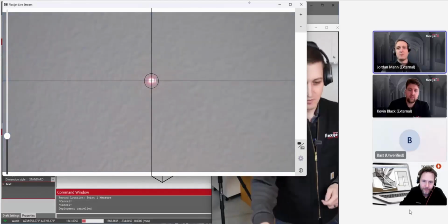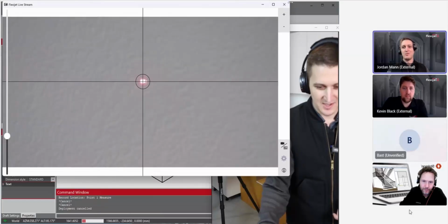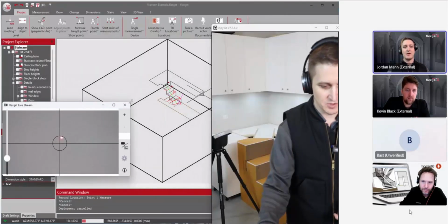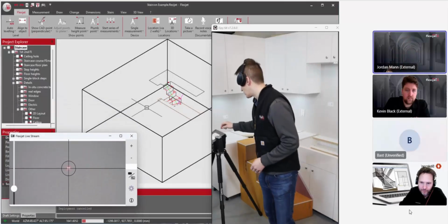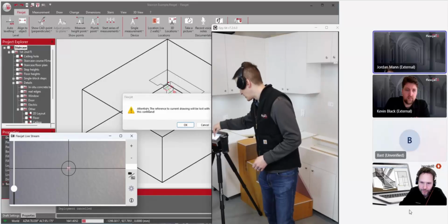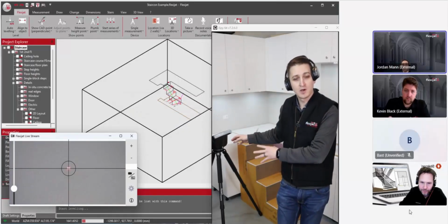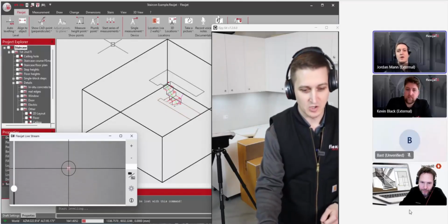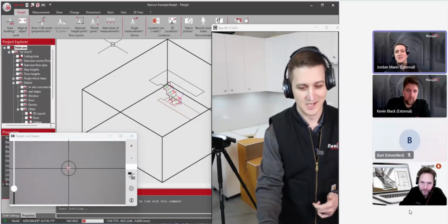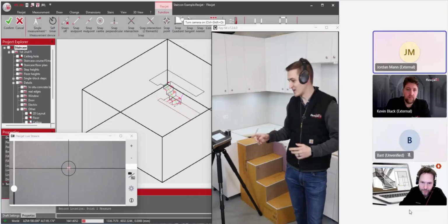So we'll start by looking at the ceiling, but in just a moment, we'll show you something a little bit different. This is Flexijet's built-in camera, the same camera we saw that was taking those pictures for us as we go. So again, we're going to relocate Flexijet. We're going to ask it to take a read of where it sits in the tripod, compensate for that digitally, and from then we're going to remeasure a couple of our known measurement points. In this case, we've set some points on the job site before we came back, and in this case, we're coming back only a couple minutes later.